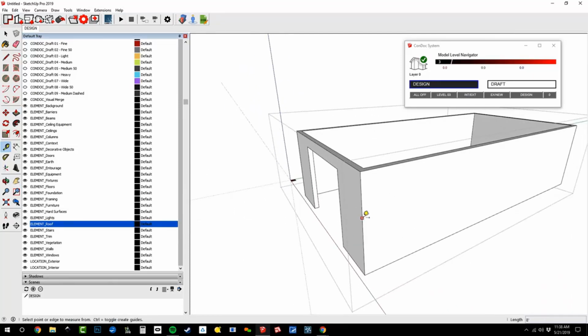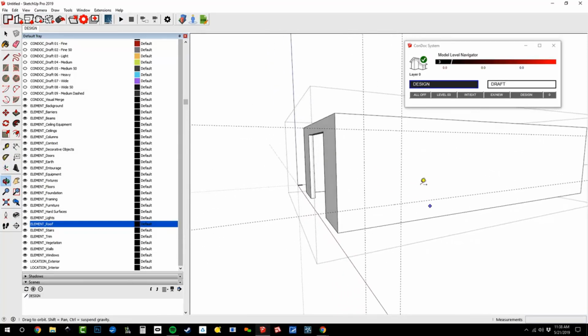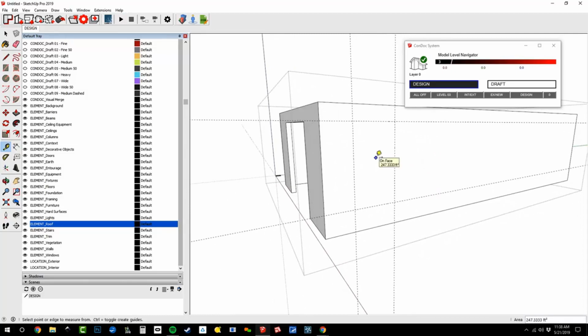Next, I'm gonna add some windows down the line here. So we'll go with like 2 feet and then maybe make them a 3-foot window. We'll make them those longer ones, like only 18 inches off the ground. And then I'm gonna tap the up arrow key to constrain on the blue and then set that window head height at the same as my garage door.